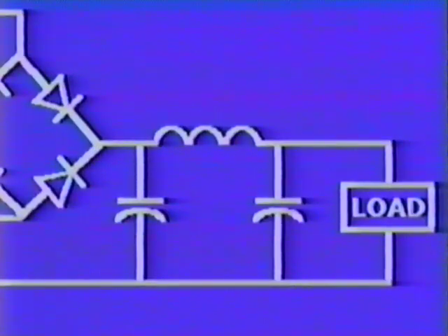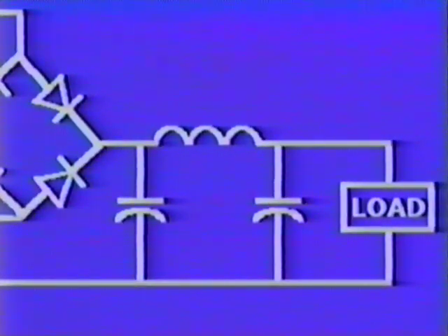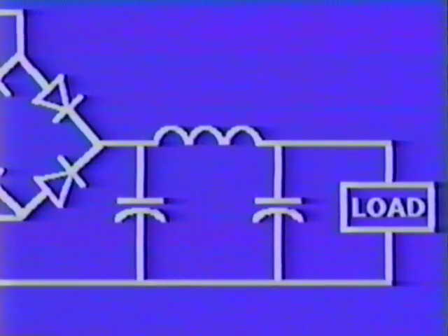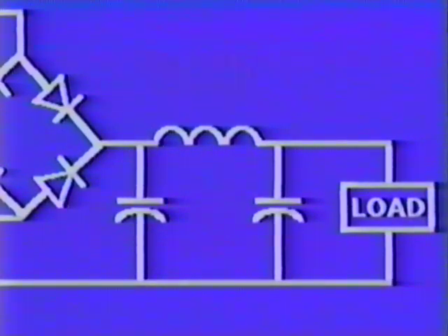There are, however, two disadvantages of using inductors in filters. First, inductors are generally more expensive than capacitors and add to the overall cost of the supply. Second, an inductor can be relatively large and bulky, adding to the size and weight of a supply. For these reasons, inductors are not widely used in low-voltage linear supplies.